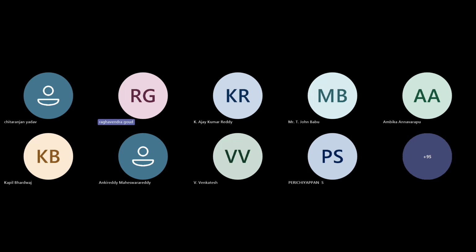Will the machine itself fill that one layer of silk fibroin? No, sir, it's manual. It's a manual process. For every layer, you have to fill that silk fibroin material, sir. Yes, sir. Manually, we have to interrupt the printing process. Before starting the next layer, we have to attach the silk fibroin on the top of the previous layer. After that, we have to resume printing of the next layers.